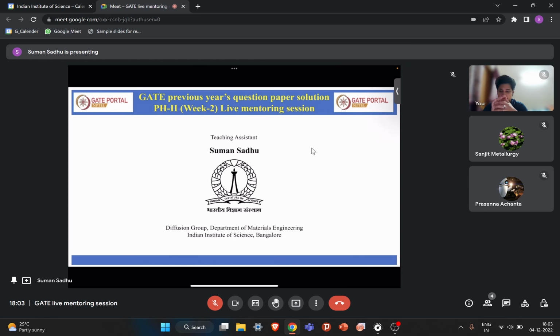So it forms sodium aluminate. Also the silica present in the bauxite dissolves in the sodium hydroxide and forms sodium silicate. So both dissolve in your sodium hydroxide solution, but all the other particles or other gangue material will get precipitated.